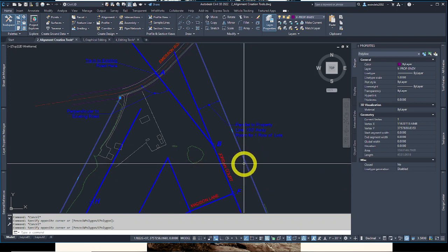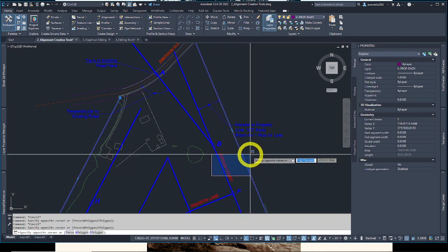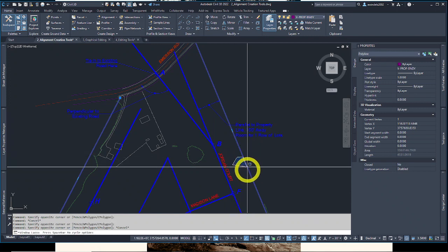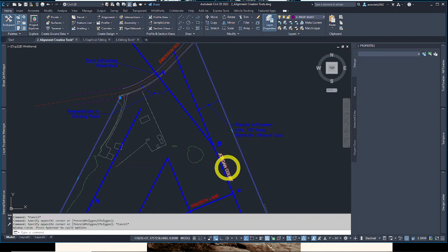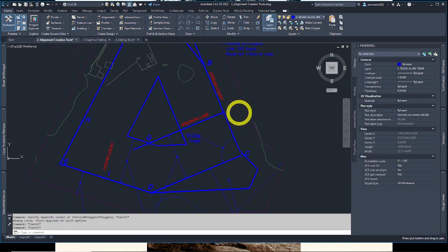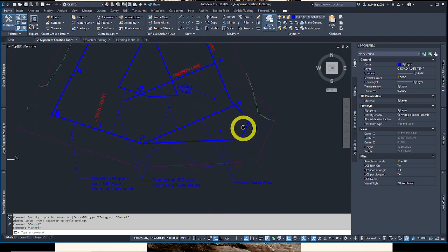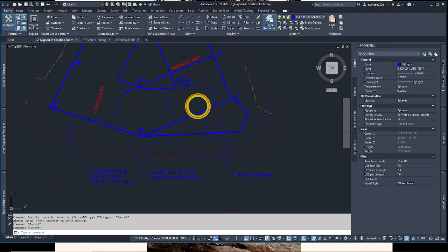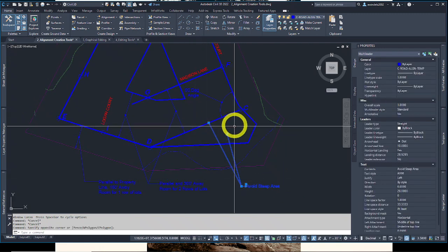150 feet away, room for one right away of lots. So he's trying to leave room here in this area for putting some lots. He wants to have a minimum distance, so that dictates this XY distance. And there's some other things. He wants this to be 90 degrees, but there has to be a curve in here. There's various things. He says, hey, or someone says, there's steep slopes in here, so we're going to have to avoid this zone.